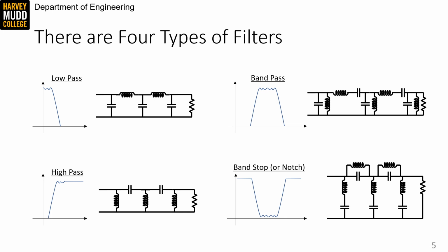They would produce third order polynomials in the filtered prototype transfer function. And that's related to the fact that the low-pass and high-pass filters have three independent energy storage elements, which are the three shunt elements. The series elements in the low-pass and the high-pass filters aren't independent of the shunt elements because they're all part of LC tanks.